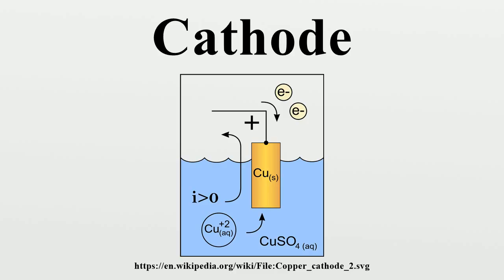These are often called photocathodes and are used in phototubes used in scientific instruments and image intensifier tubes used in night vision goggles. Diodes. In a semiconductor diode, the cathode is the n-doped layer of the p-n junction with a high density of free electrons due to doping, and an equal density of fixed positive charges, which are the dopants that have been thermally ionized. In the anode, the converse applies. It features a high density of free holes, and consequently fixed negative dopants which have captured an electron.